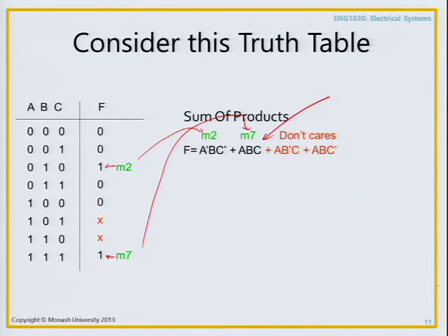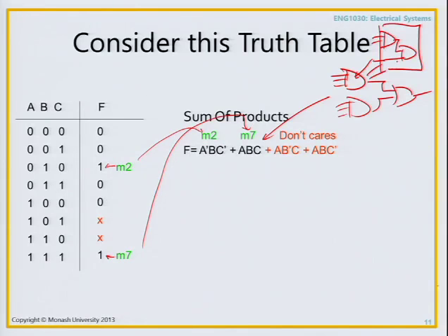How many inputs does this have? Well, this requires 2 AND gates, each with 3 inputs, and an OR gate to put them together. That's fine. Now, how are these constructed? Often this 3-input AND gate might be constructed as two 2-input AND gates, as we saw previously, and that might be what's inside that box.